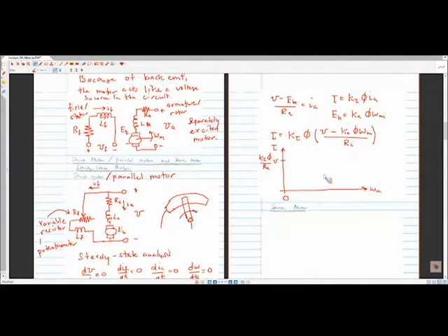So eventually you get to the no torque speed. And so basically your motor starts spinning so fast it is unable to generate any torque. This is the case, of course, in the no load condition. This is just a motor. I have it on my desk, put a voltage across. There's nothing actually slowing the system down. We're not even including damping in the system. And so if you then solve for when torque is equal to 0, you would get k tau phi over Ra times V. And then in between, we know this linearly decreases.